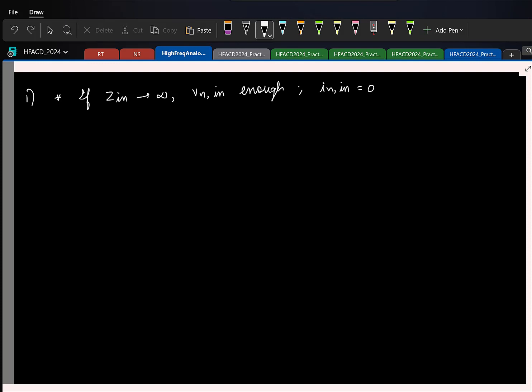Right? So this is nice because if you think about it, in all the possible candidates we have for making an op-amp, the input is given to a gate. So if you ignore the gate capacitance, the input resistance is infinity. So to model the noise in all our op-amps, strictly speaking, we only need a voltage. I'll just write noise in op-amp. This is assuming the gate capacitances are ignored, right?